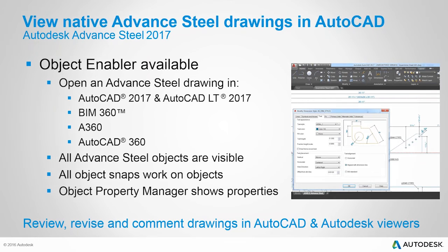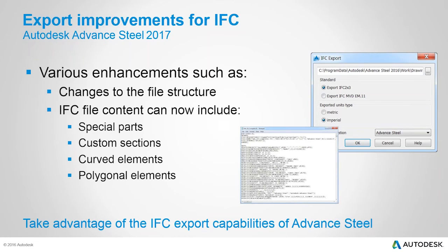Then we've got further enhancements for other products. The UK BIM standard, and probably most other BIM standards, refer to the IFC file format, Industry Foundation Classes. The standard actually says use the best possible format available with the most intelligence, and we'll come on to that in the next slide perhaps. But they usually refer to the fact that if you can't find anything better, then at least give them an IFC to exchange data. It's sort of a lowest common denominator.